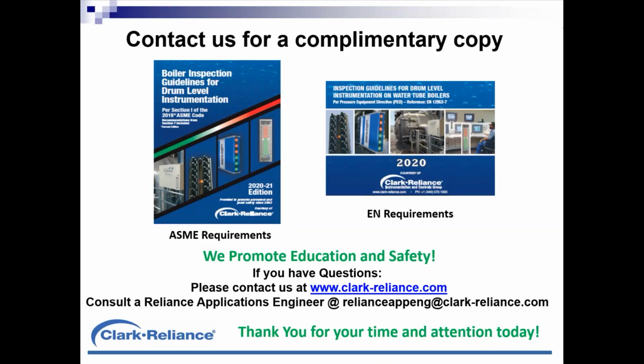Well, again, it would apply to which code of construction you're following. If they're following ASME construction, you've got that limitation of 900 PSI. That limitation is not in the EN requirements. So first of all, which rule of construction is being applied on that boiler? That would be my driving concern.